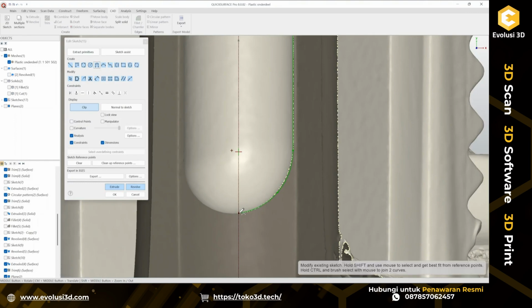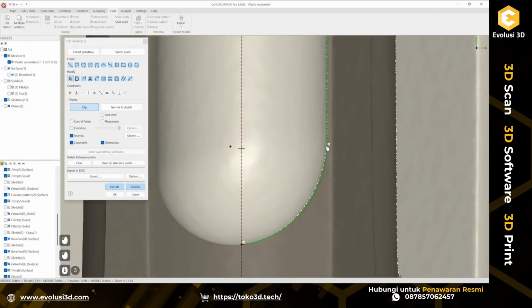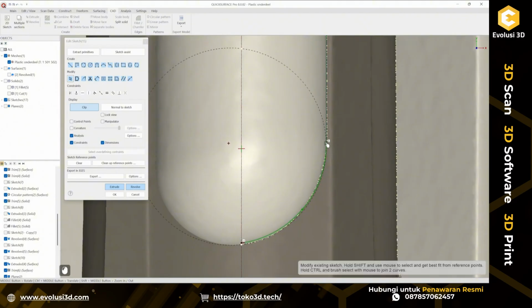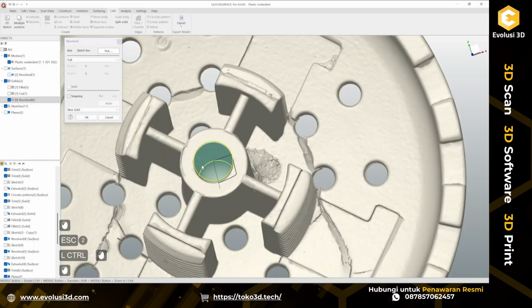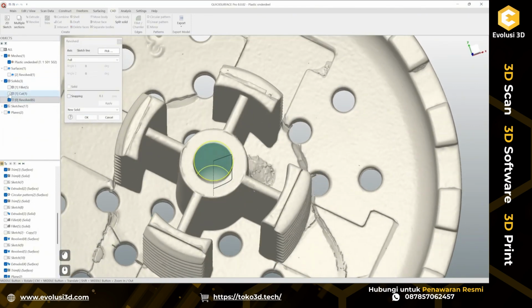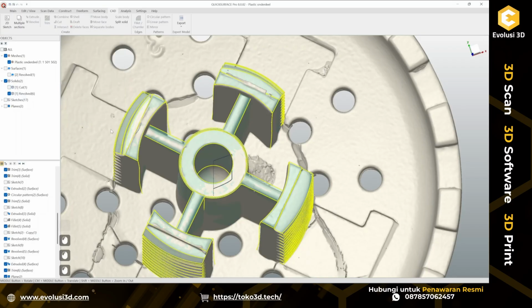and there to work this out, I will just create a tangent arc here, and I will snap it onto axis. Okay, so probably on this side we can try to move it slightly to get like average. And let's just close this profile so we get this as a solid part like this, and at the same moment we can do cut operation instantly.